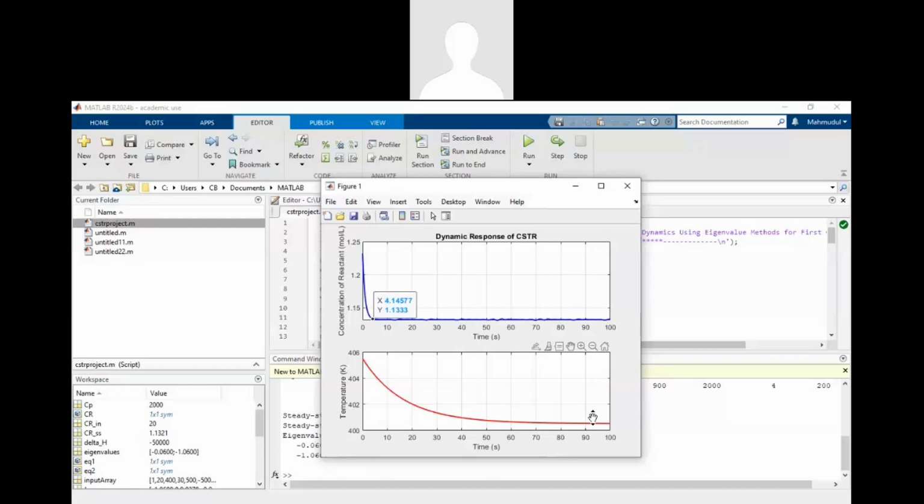However, it is important to note that this model is only applicable for linear perturbation and small values of heat transfer coefficient. If the perturbation is non-linear or the reaction order is higher than 1 and the heat transfer coefficient is very large, approximately 50 or higher, then the model becomes unstable and the system, especially the temperature, increases unboundedly and diverges from stability.